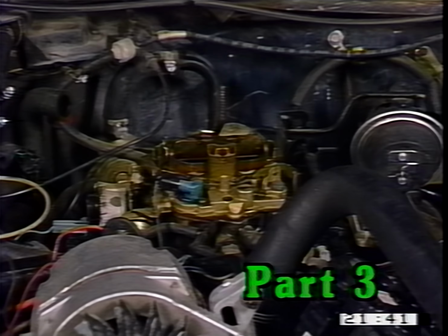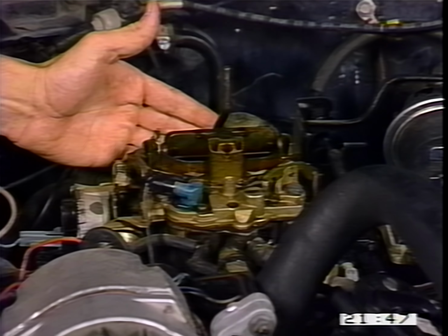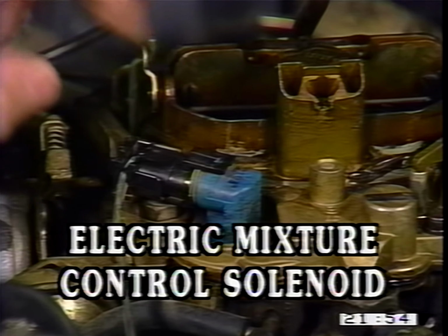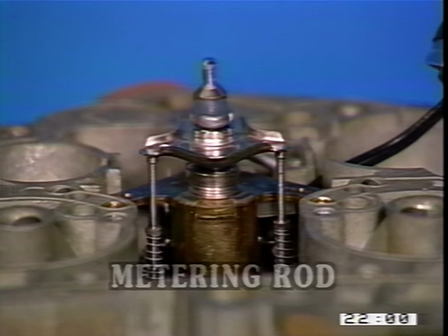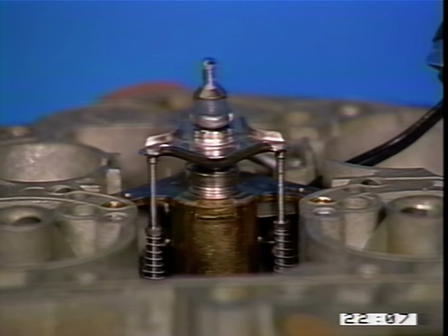This full-function carbureted engine measures 3.8 liters, 231 cubic inches, and is equipped with a feedback carburetor, as are all GM carbureted engines having a system computer. This system uses an electric mixture control solenoid. This solenoid operates a metering rod system in the float bowl. The metering rod supplements fuel that is supplied by the idle and main carburetor systems, which vary the air and fuel ratio to meet specifications.